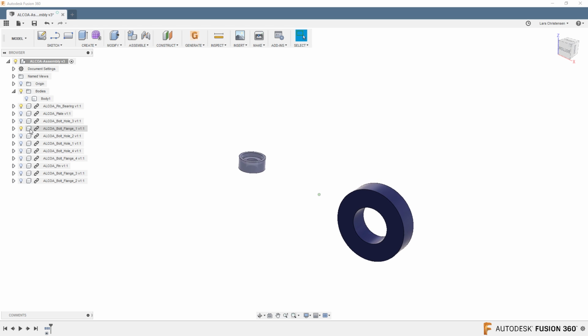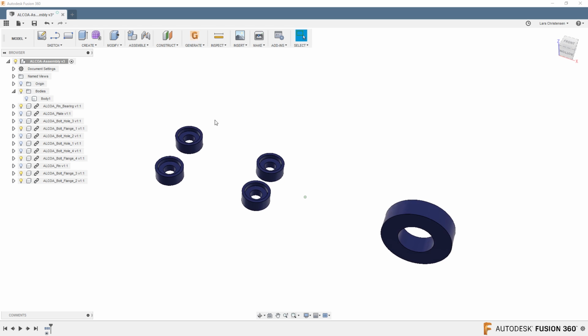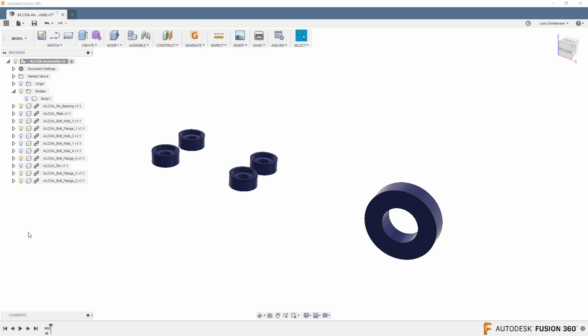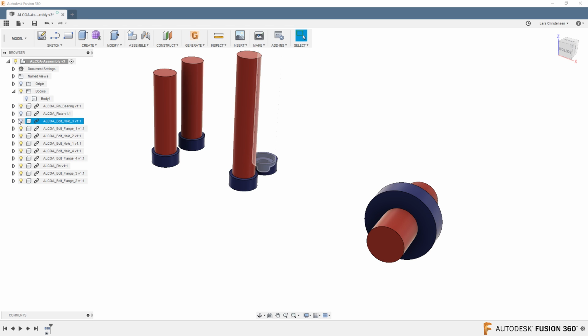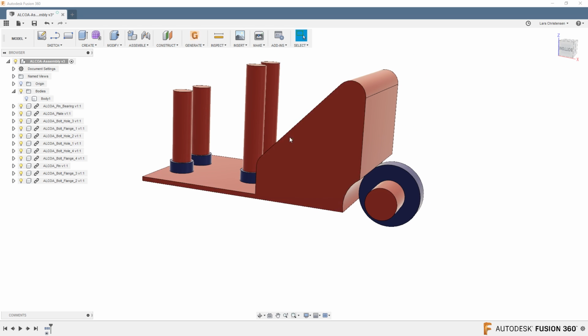And that is our preserve area. So this is actually where the load's going to be and where the counterbores are going to be. Just going to find them. I should have labeled these better. Bolt flange is actually what they're called, so I can probably find them by the name. There you go. So these here are the areas we're going to preserve inside. We're going to tell the software to preserve this. And then we're going to tell it the other areas are areas where we don't want you to put any material, because we need those areas not to have any material.